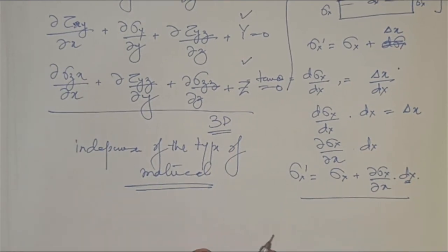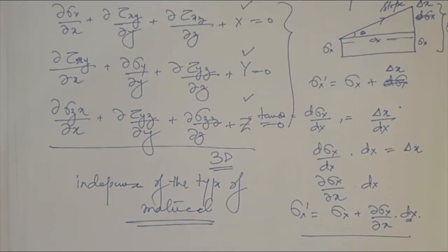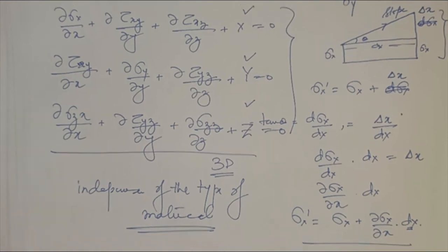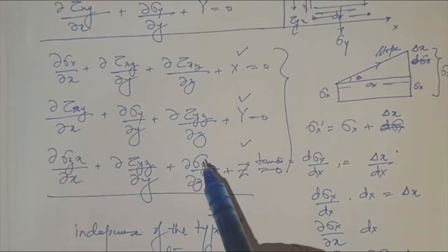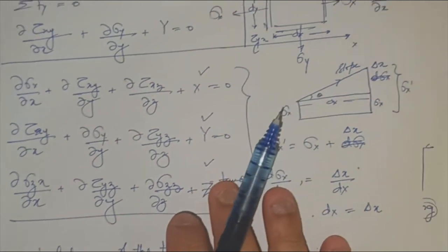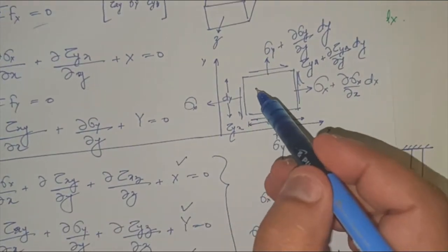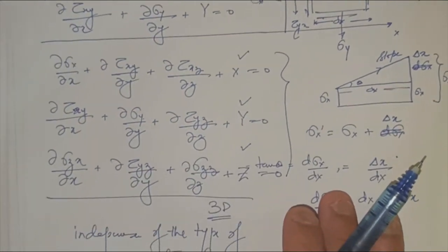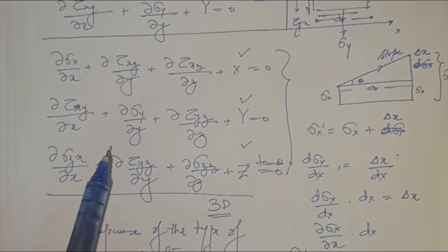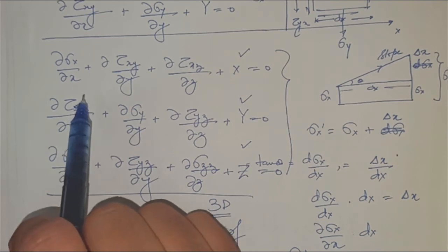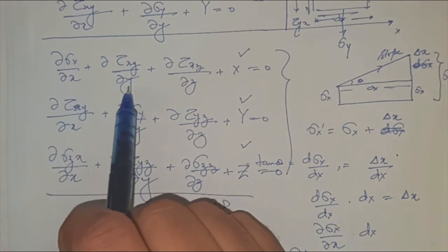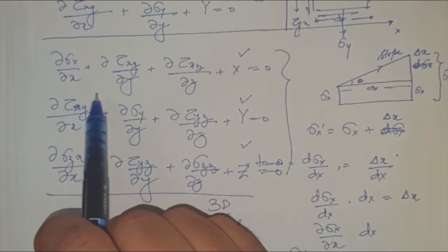Material dependency will be shown by the stiffness of the material, also known as Young's modulus, and we'll be talking about the Young's modulus afterwards, not now. But you are very much aware that these equilibrium equations will be valid over the surface of the body. They will be valid inside each and every point inside the body, and they do not depend upon any material. Just a differentiation of the stress tensor with respect to x, y and z.